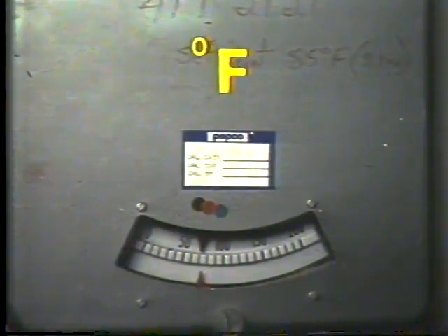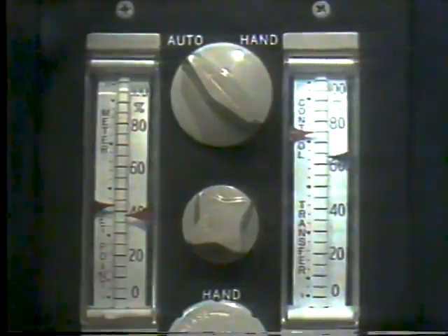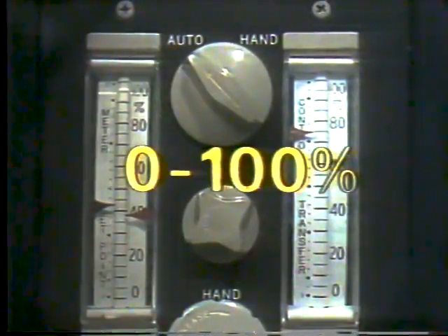When tuning this system, the technician had to relate to both temperature indications and percentages. This is because most of the instruments in this system indicate percentages of the temperature range rather than actual temperatures. For example, the cooling water temperature transmitter's output is in degrees Fahrenheit, while the hand station gauges indicate temperature in percentages of 0 to 100%.